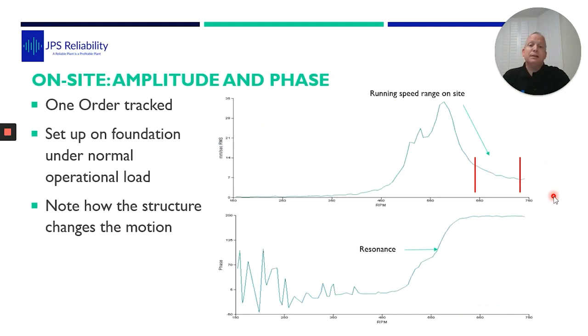So we did a follow-up test. And here we have these low range 180-degree changes. But look at this here. Massive sweep through two resonances. And on the bump test, we had those two resonances close together. So this is matching exactly on the pump. When it's in there, it's doing that. It's moving on the floor. Here is our under speed, which shows the faster we go, the further we move out from the resonance.